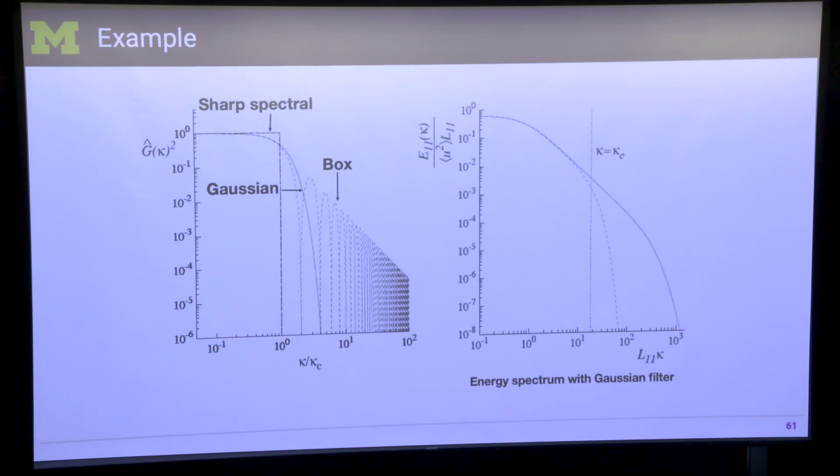And if it's a spectral filter, it will not work in any spatial simulation when we solve partial differential equations. You can only use a spectral method to solve it, which only works if it's a periodic box, which none of the gas turbine combustors are, right? If you have an inflow and an outflow and a complex geometry, you cannot do the spectral filtering. You have to do what is called box filtering. And when you do box filtering, that sharp line that I drew no longer exists.